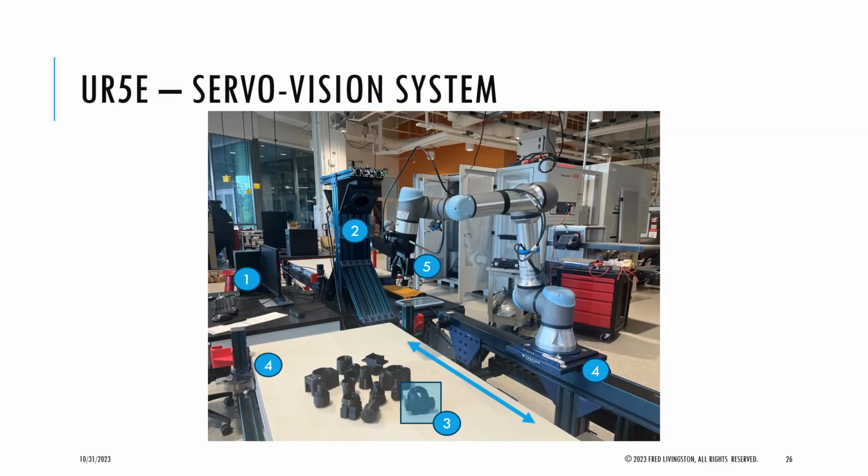And so if I set those two equal to each other, and then I do the inverse kinematics, I will get back my Q1, Q2, Q3, Q4, Q5, and Q6. And if I program my original Q values, this is my goal, and this would be my current location. This is something called Q0 or something.